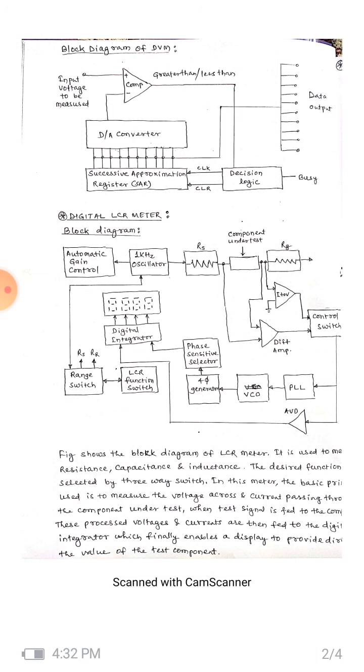Next one is the successive approximation register, that is SAR. The basic function of this is that it generates the binary pattern with indicated weight, and the SAR is used to control the DAC and the estimates here. And next is the digital to analog converter.